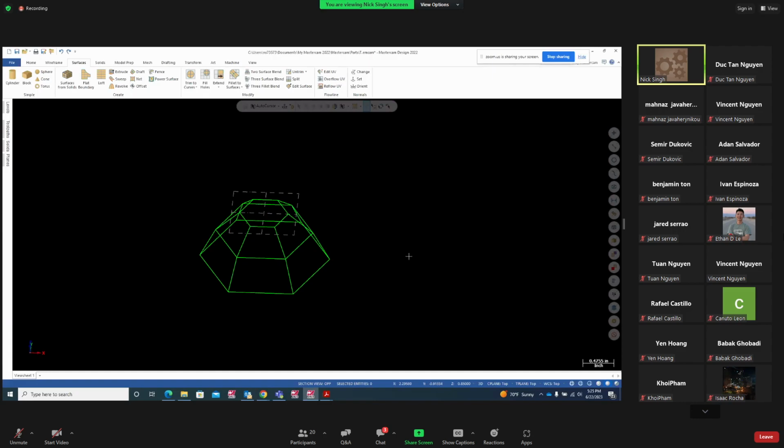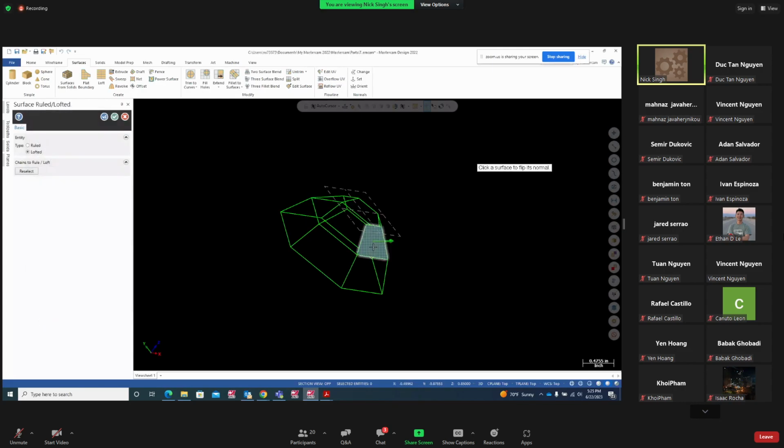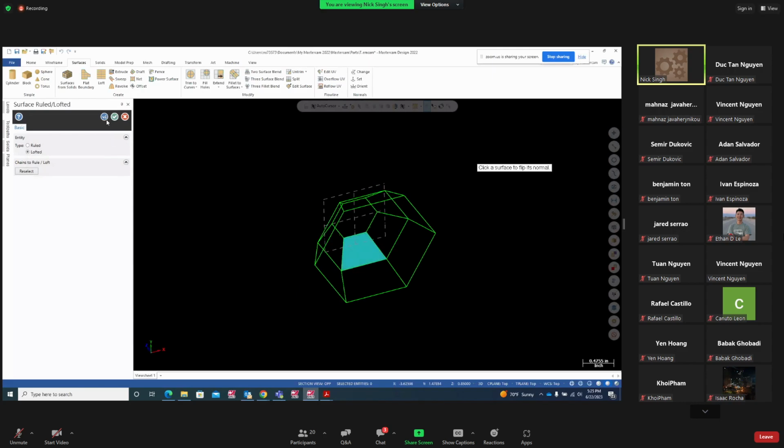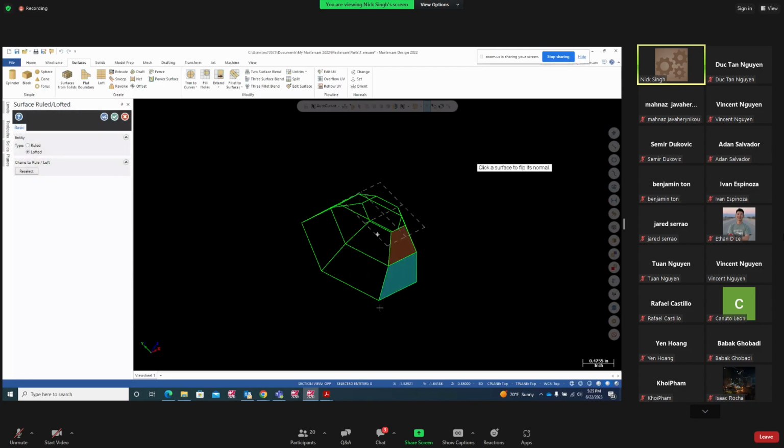So to do the surfaces, go surface, loft. I can go single, this one. We can pick this entity also. Start point, end point are the same. Start, end point is the same. So I can go single, pick this one or this one, same thing. There. Or you can go single, this one and this one, same thing, because endpoints are the same. Open that.